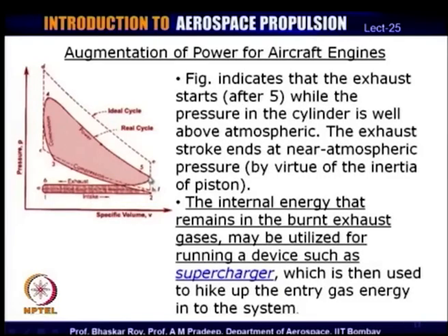So, the difference between the exhaust pressure and the intake pressure starts going up, as a result of which this loop which we see here, the intake exhaust loop, starts consuming more and more. This area becomes higher and higher, which is the non-productive or non-power creating loop of this cycle, as a result of which a lot of power that is produced actually goes into this loop, and it is not available at the end as BHP. Now, this is a problem, and as a result the available BHP would go down.